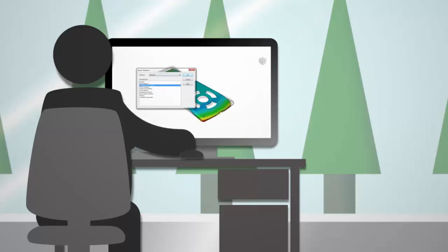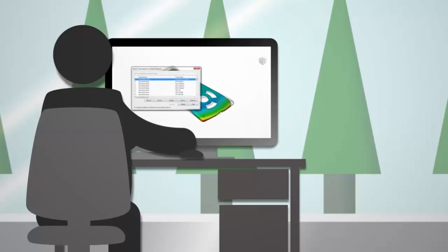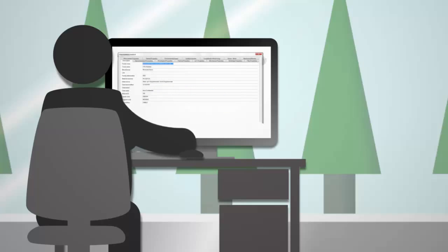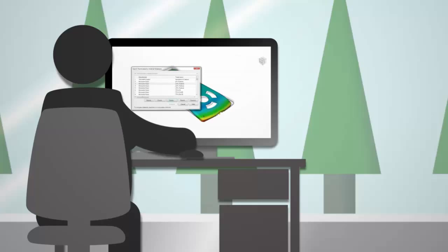You can consult the material database within Insight to find an appropriate replacement. The database provides information on a material's shrinkage properties and recommended processing conditions. You can search the database and display a side-by-side comparison of potential materials, so you can find the most appropriate match, and then run the analysis to verify the new material's suitability.